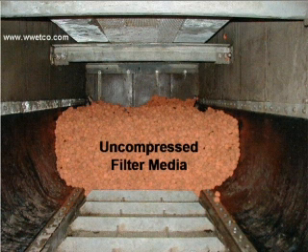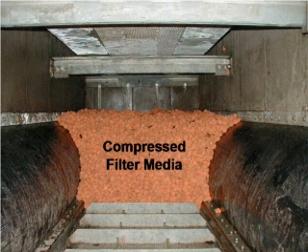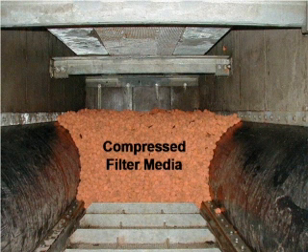This picture shows a wet weather event where the water level has increased and gone beyond the dry weather treatment capacity. It's flowing through the filter now. The filter's under the grassed area. There's no grass there right now, but it has grass now. And then you can see it boiling out of the effluent, that white area that's coming out. That's after filtration and UV disinfection. Not all of the flow is disinfected, though. But the flow control basically causes about a 3-foot differential head to push the flow through the system.